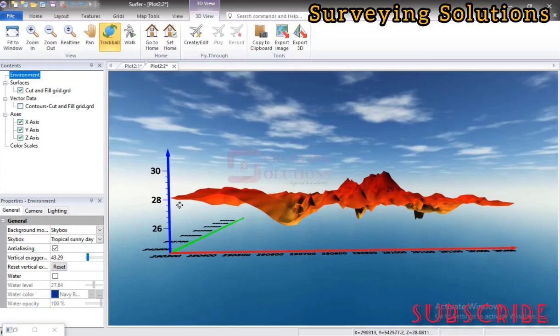Good. So from this, you can see that all of those values you have above 28 are going to be cut because they are above your lower surface, and all of those values you have below 28 are going to be filled because they are below the lower surface. So by the time you cut this volume of material off and use it to fill these spaces here, you are now going to have a uniform terrain of 28.